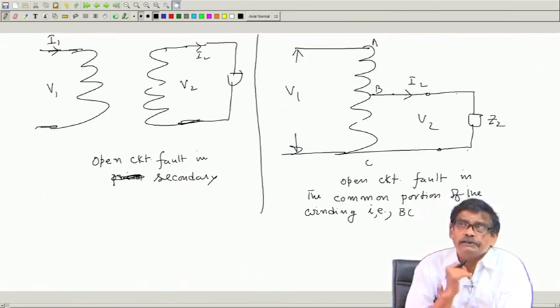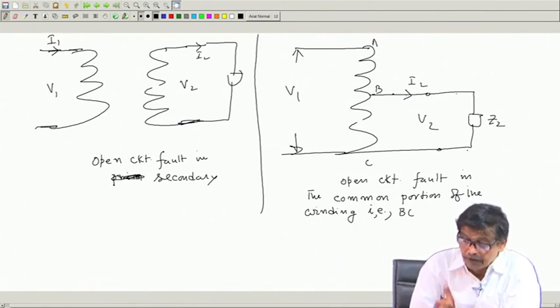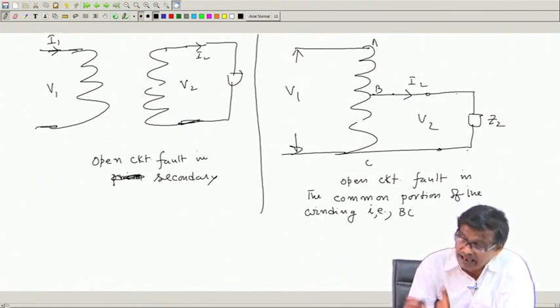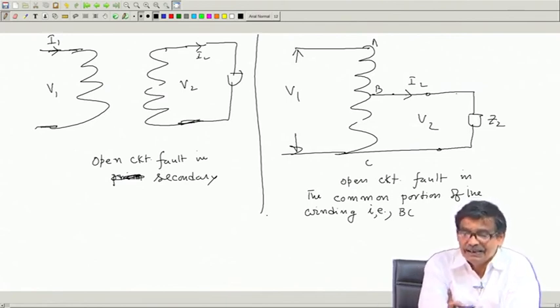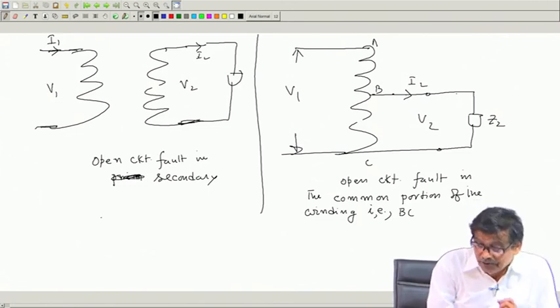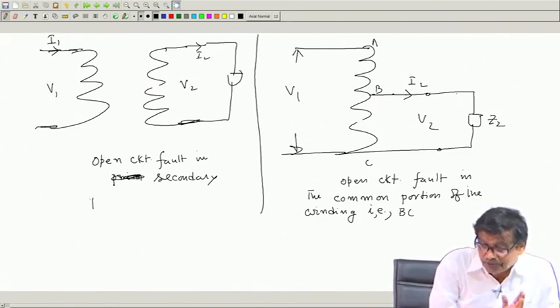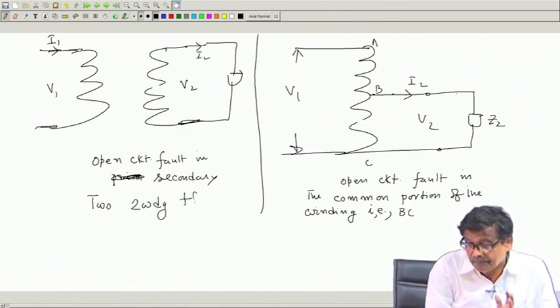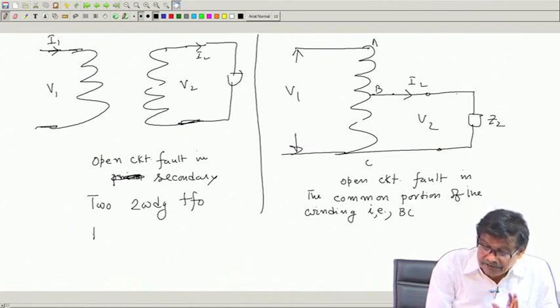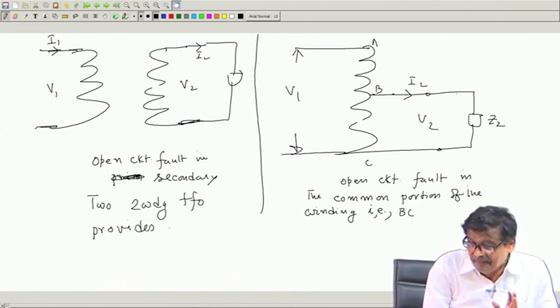and this problem is called isolation. So, an auto transformer does not provide isolation. Here, if such a thing happens, the load is isolated from the primary. So, isolation is the biggest point: the two winding transformer provides isolation.